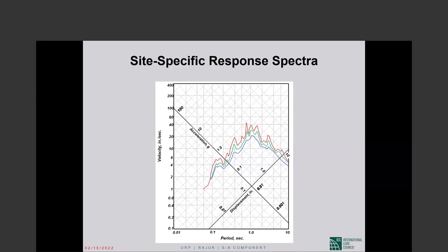If you hit the structure with another ground motion and look at the spectrum, there will be peaks and valleys, but at different locations, at different periods. So those peaks and valleys don't have any significance for design either. Those peaks and valleys are peculiar to the particular ground motion. Another ground motion will give us peaks and valleys somewhere else. So we smooth out those peaks and valleys.